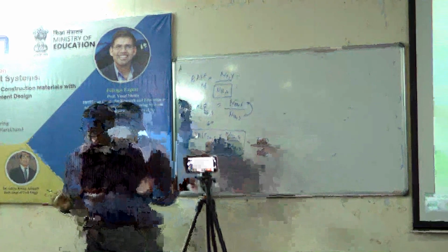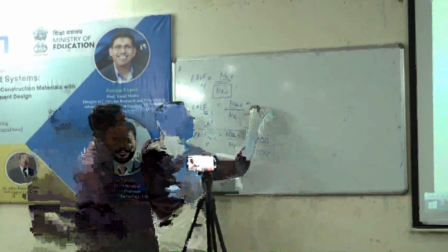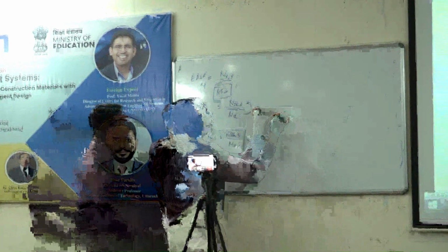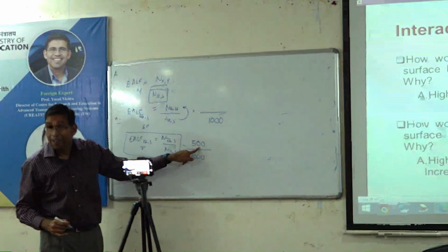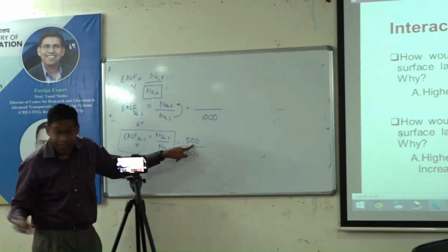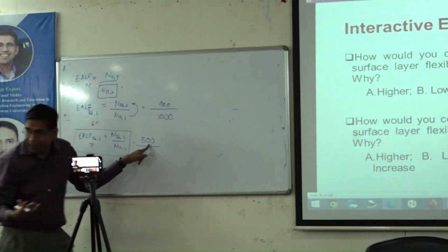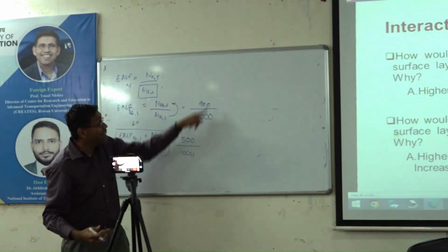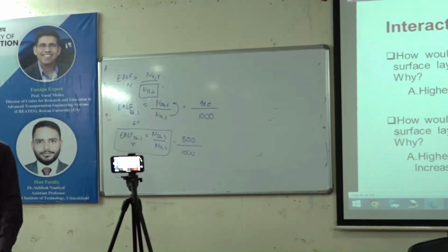Understand that? It damages in fewer passes. The stronger pavement handles this better. You build it, and at 36 kip it will not fall apart that easily. That number will be closer to 1,000. I'm just giving a number like 900, because a stronger pavement can handle the change in loads better than a weaker pavement. Can everybody see that?